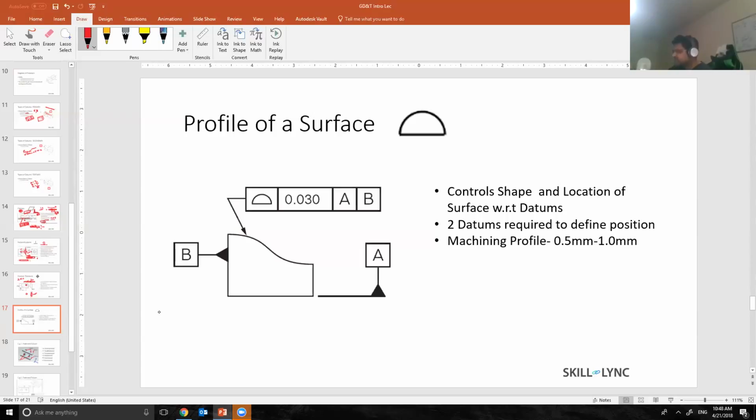It can go inside the screen perfectly, because I have not constrained the third surface. So it is a 5 degrees of freedom constraint, but one translation is not constrained. That is, it can slide outside the screen, it can slide inside the screen, but it has a nice wave to it over here like this. And because of visual aspects, I have to control this wave over here.